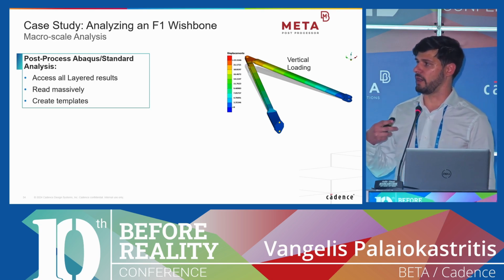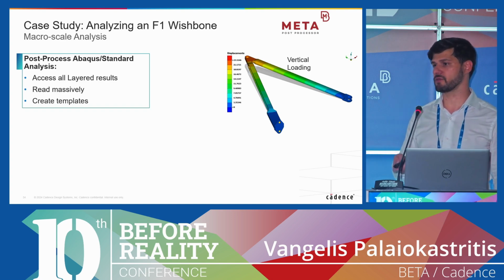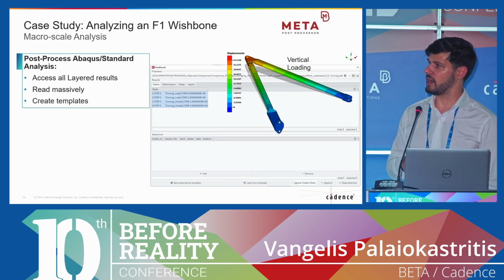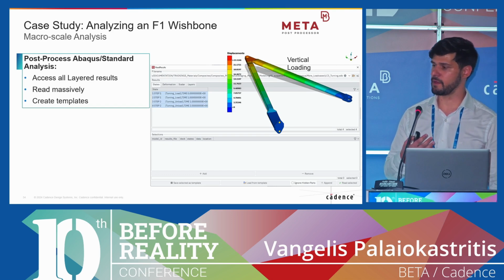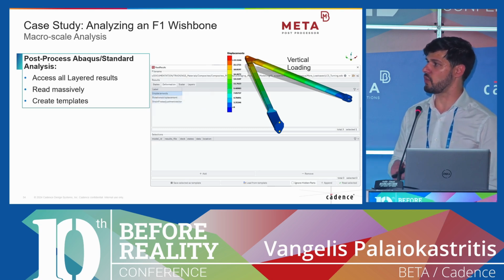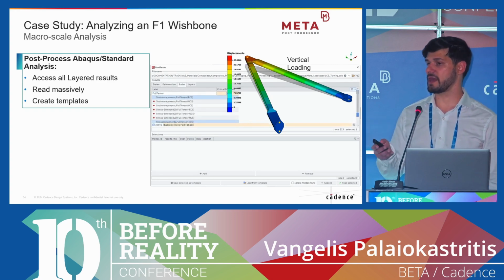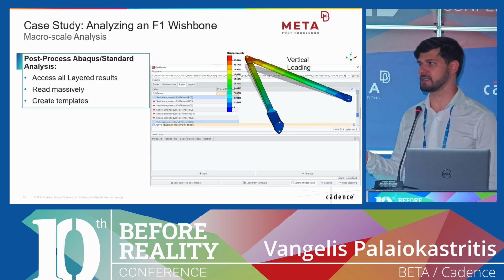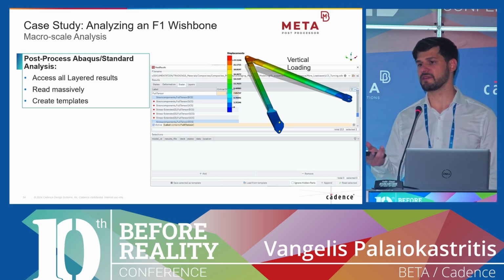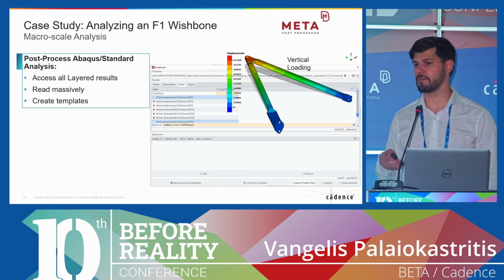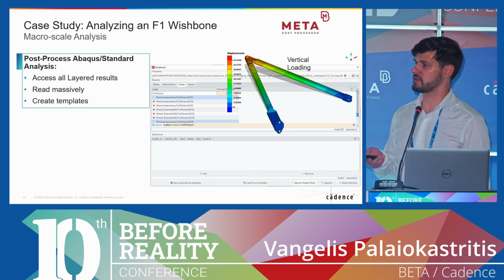So with the redesign of version 25, we also introduce a dedicated tool that allows an efficient approach in reading and accessing layered results. The user can select all the types of layered results that exist in the output database, stresses, strains per layer, or even failure indices or reserve factors or any other solution-dependent variable that can be calculated by the structural solver.